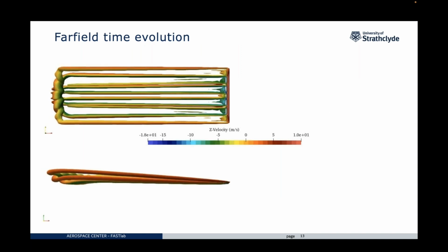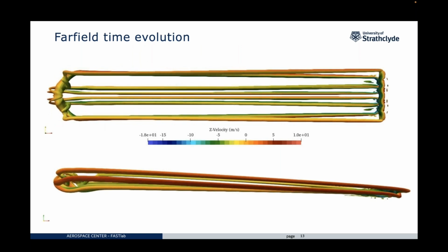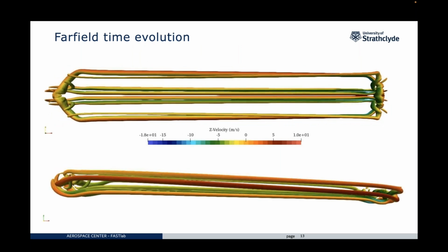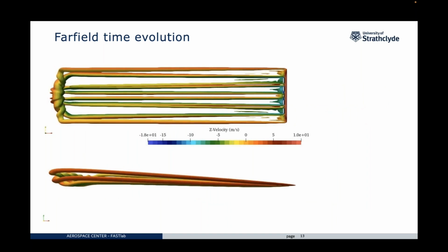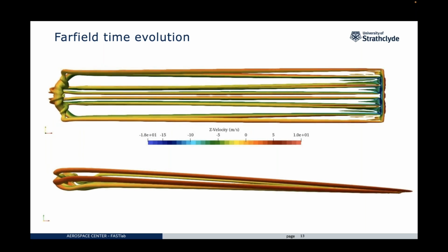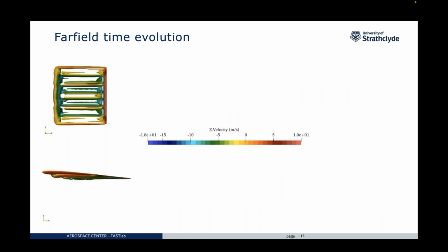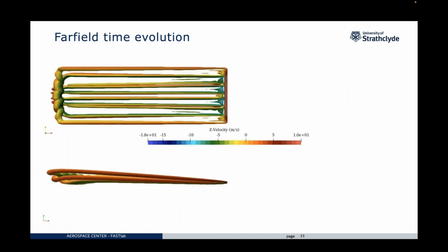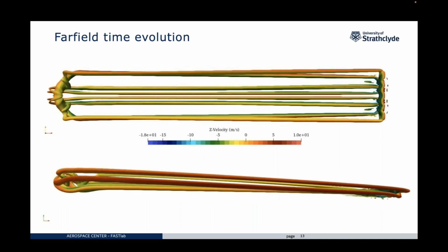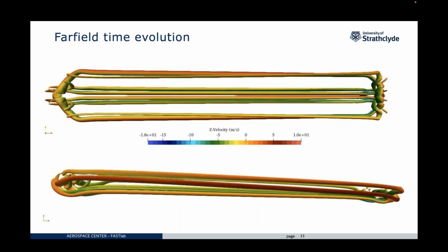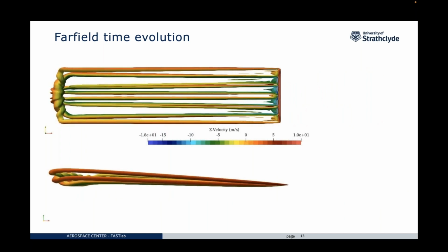So going from left to right is the lifting line, and upstream of the lifting line is the generated wake as a result of the line moving through the domain. So you can see here very clearly the two distinct regions. This one here corresponding to the inner flap vortices, the outer flap vortices, this region here, and then we have the tip vortices here. And we can see that in time, from the mutually induced velocities, they are observed to move downwards. And that is consistent with what we'd expect. And that's why it's a danger to structures as well as aircraft.